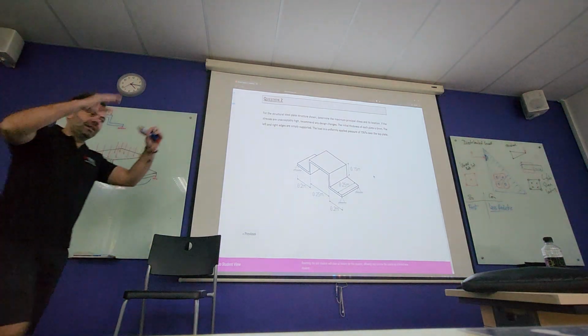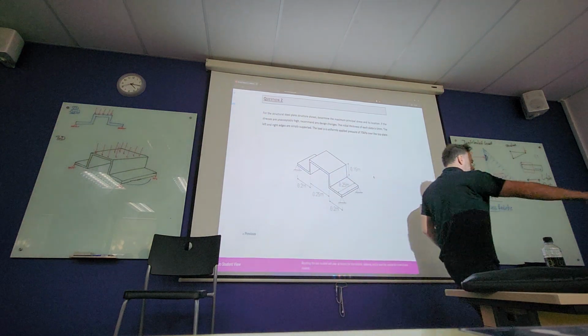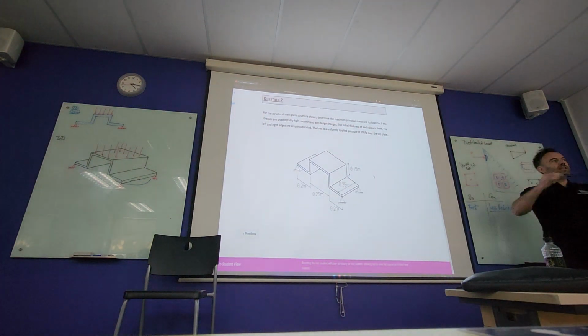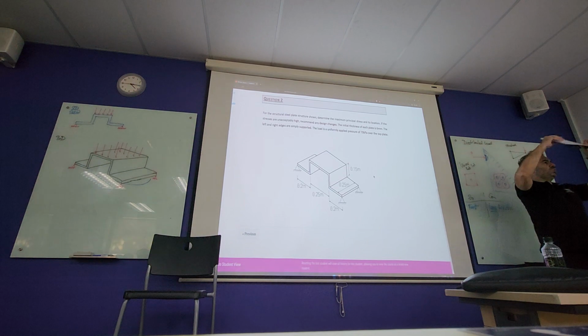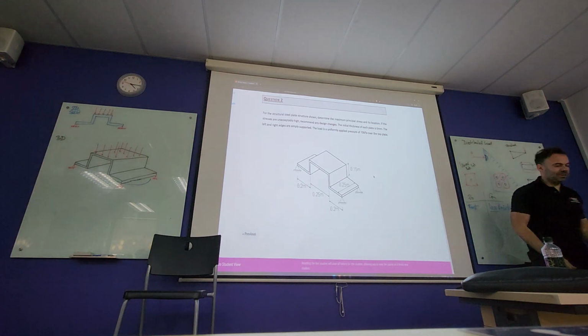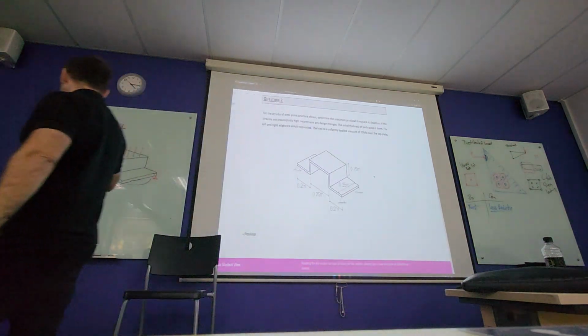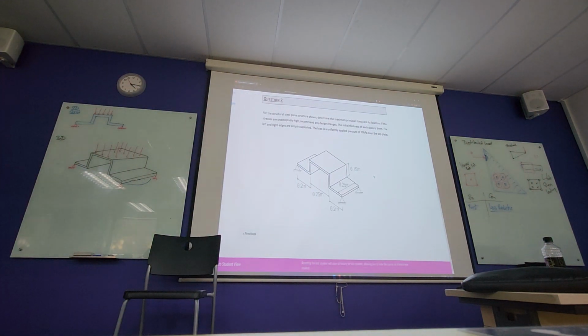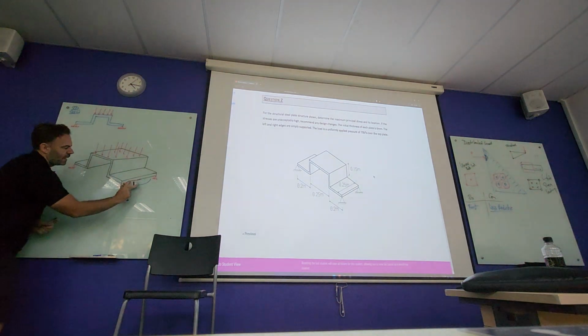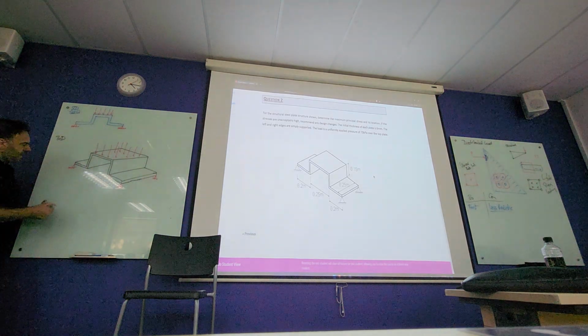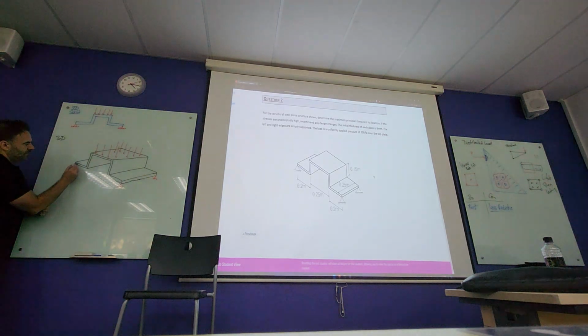Remember that story that I showed you with the sheet last time? Shells like to be loaded like this. That's their job. They love doing that. So how would you then go and model this? Normally, there are other ways, but normally what we model is the mid-surface. So we will go and model a surface that goes like this.